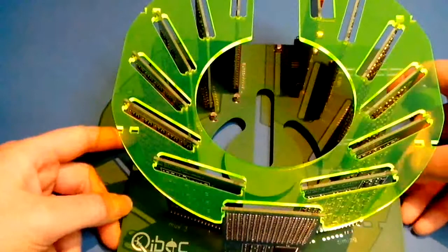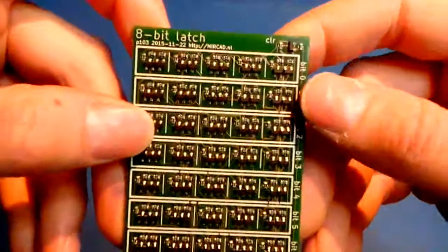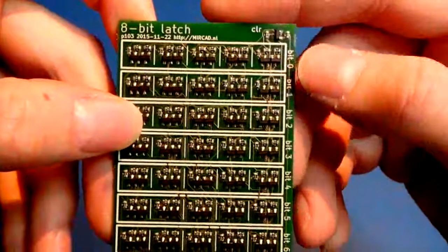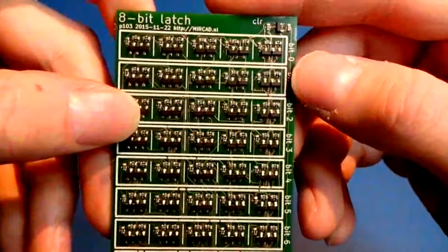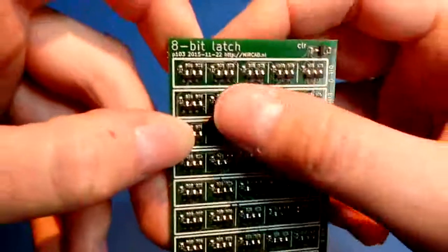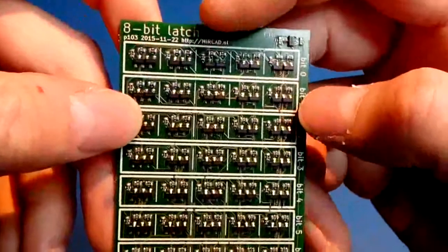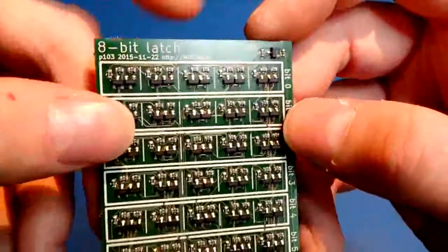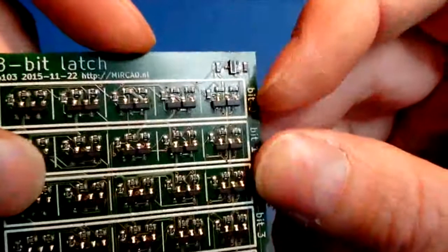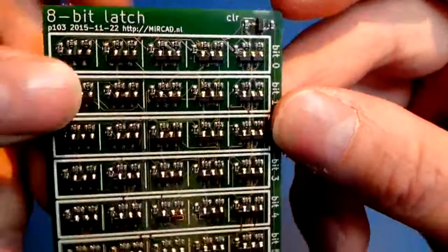It is a 16-bit double address latch, so you will need 4 8-bit boards. If you look a bit more closely at this board, well, the name says 8-bit latch, and it is implemented using the same subcircuit 8 times, as you can see, 1 time for each bit. So each row is a duplicated subcircuit. Each cell within each row is a logic gate. And if you look closely, you see that within each cell, each logic gate consists of 2 transistors and a number of resistors. It is not very important for now, it will be discussed in another video.